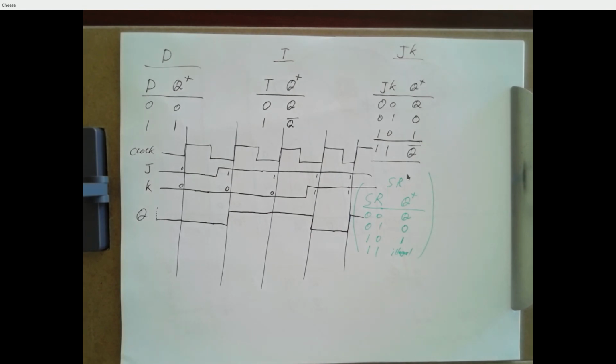So how do you know when you have to factor in the setup time and the hold time? Ah, now that's another question. So there's a homework question on that. It asks you to draw some windows around these. So we get to fortunately ignore that for the most part. All these questions that say analyze, draw a state transition diagram, things like that, we're mostly ignoring setup and hold time, or we're assuming that the clocking is done reasonably well.